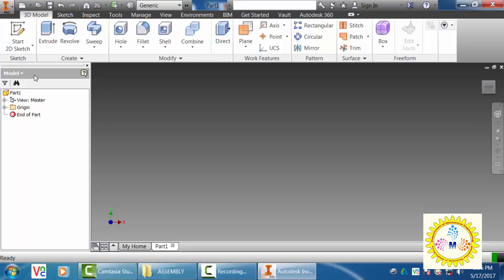You don't select the x plane, right? If you draw there, when you finish off the drawing, the model will be lying on the horizontal plane, means the body will be lying horizontally. Instead of going for the x plane, if I choose the y plane, the complete model will be standing vertically. So it is better to choose the y plane while drawing every part in the screw jack.